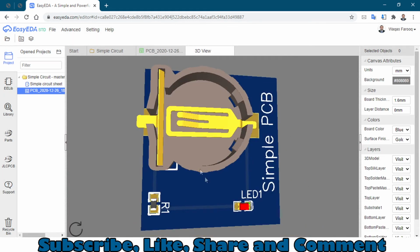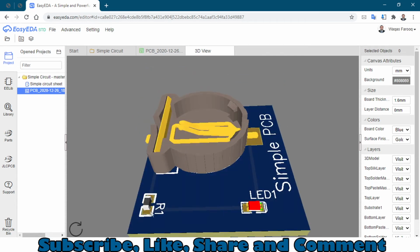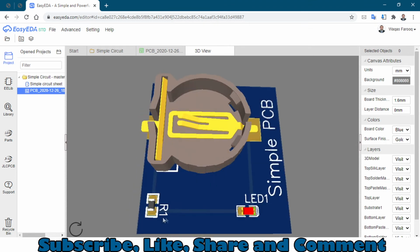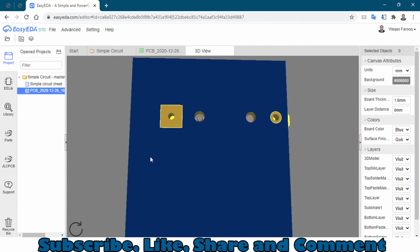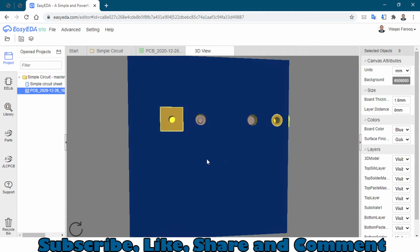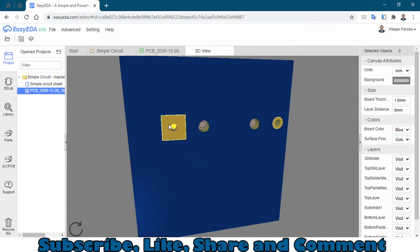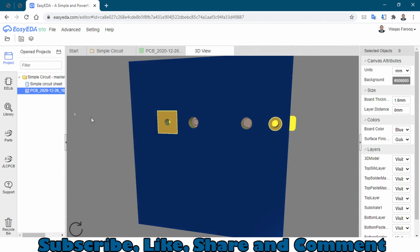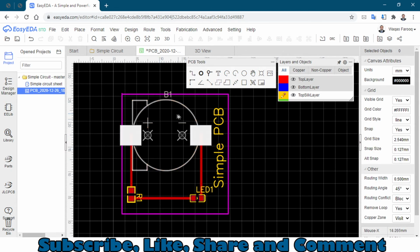Here we have the battery, and here we have the resistor and the LED, and this is our text. You can check the back side. As you can see, this is a soldering pad we added, and here we have a circular pad and a rectangular pad. But if you want to remove those, I will just delete them, and this will be on a top layer.